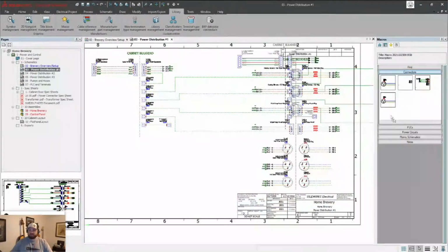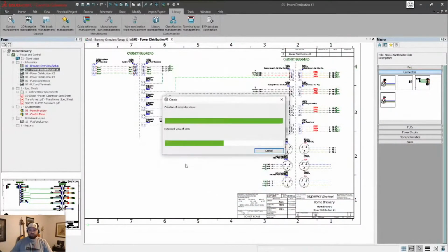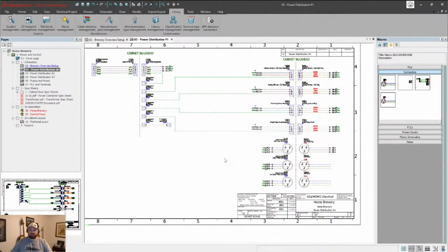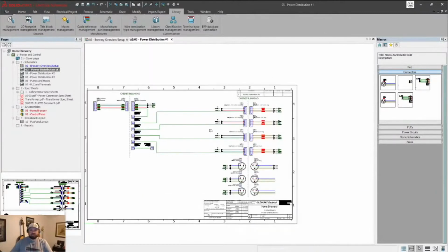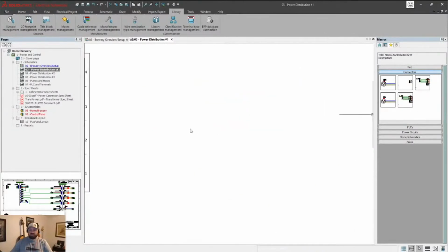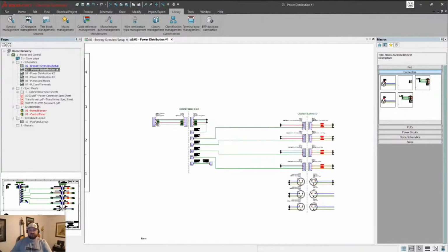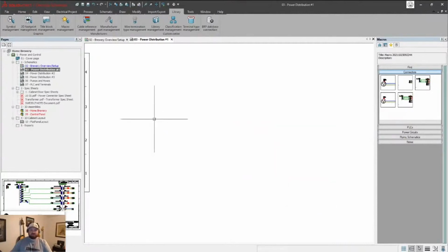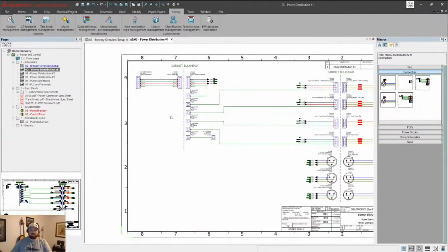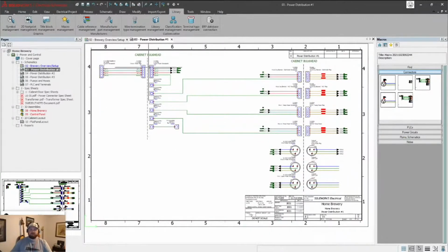And now I can drag this over. And now when I'm ready to, as soon as my computer catches up with me here, there we go. I can go in and I can drag that into place over here. But I'm not going to do that because it's going to add all those new components to my project. But think about that real quick. How many connectors are on this screen? How many pieces of manufacturer part information? All these origin destination arrows, as long as they're on the same screen. All that information is captured in essentially a new symbol. It's a circuit that's saved off that everybody can use going forward.